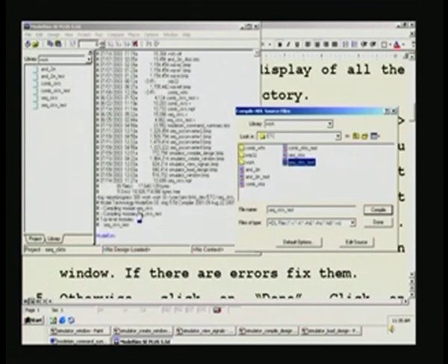Now, you see it has done the compilation. For example, compiling module sequential circuits, it has taken the design first, and then it has compiled the module sequential circuits test bench. The lower ones are always compiled first, and then it moves up to the top, and the top happens to be the test bench. That is why it has been done here. This module is in the work directory. So, you have a top level module name also here, it is not .v or something. This is also an important thing that you should take care of while loading this design.